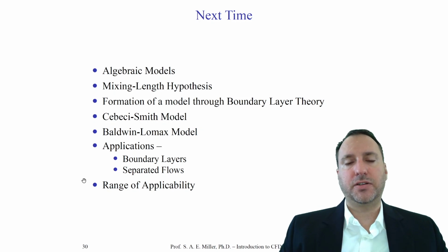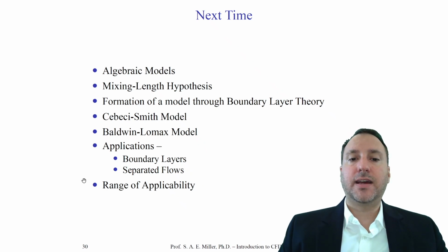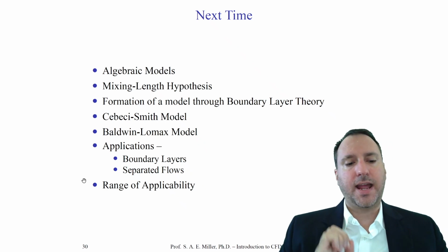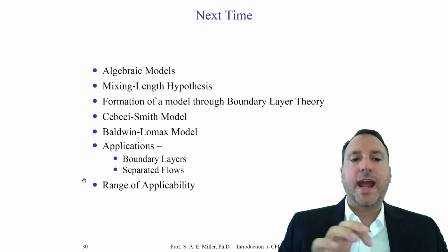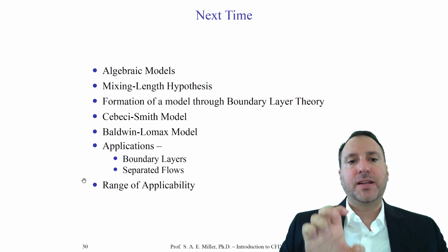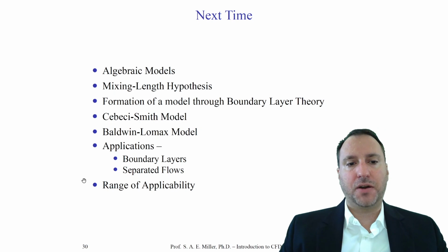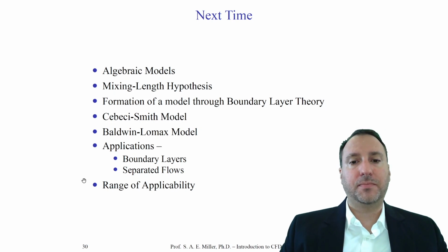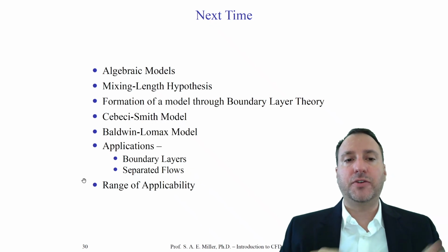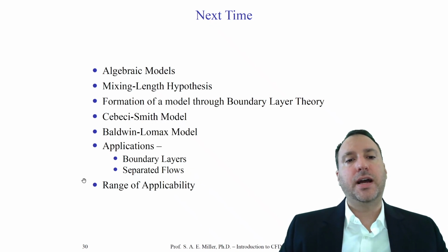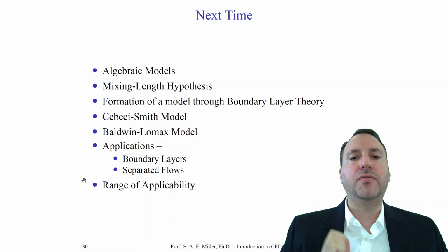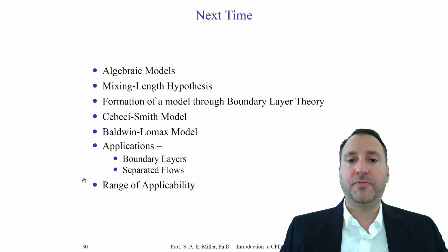So for the next few classes, we're going to take the RANS equations and the fundamental theories of turbulence from boundary layers and isotropic turbulence that's homogeneous, and the length scales and averaging properties and statistical techniques, and apply them all seamlessly to create these particular turbulence models. And then, of course, we're going to look at the implications. We'll do this for the next couple days. Remember, in your CFD solvers, you'll be able to choose these models, and you'll have to know the equations being solved, their assumptions, and what type of flows they're valid for. It's easy to make a bad choice.